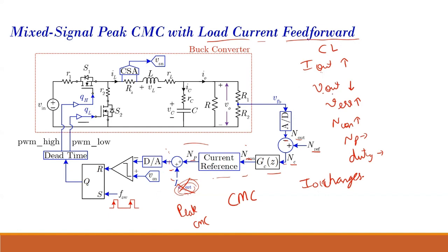See, when there is feed forward, what happens? The effective reference current is changed almost instantaneously, and so it will improve the performance. In case this was not there, for the reference to change, it will take some time. It will go through the entire process, and because of that, it will slow down. But if you can directly give the information and directly change your effective reference, then it will improve your performance.